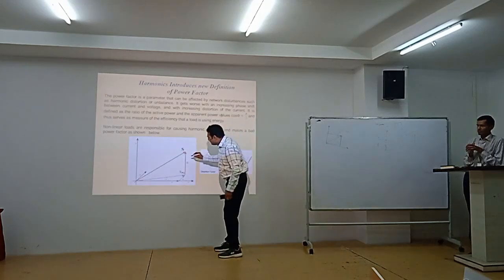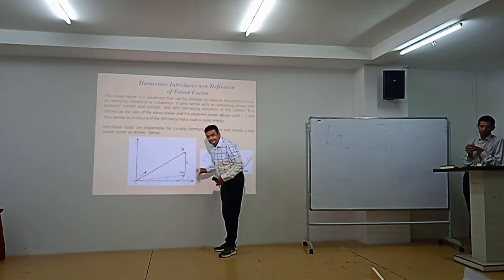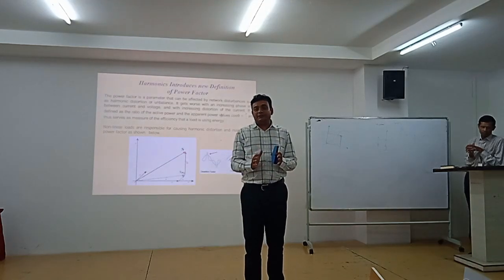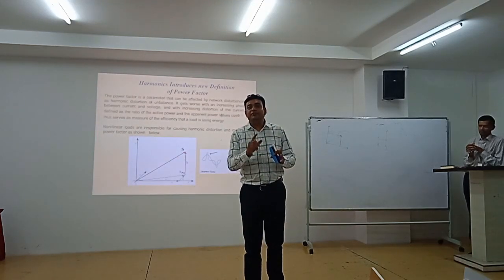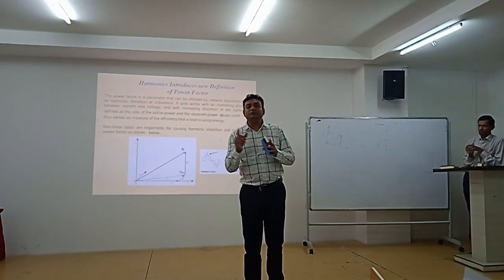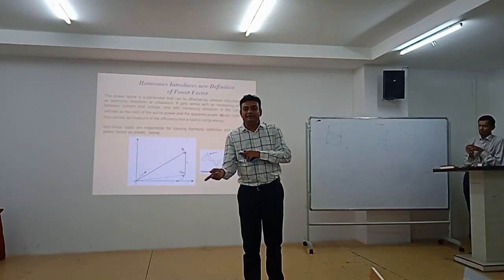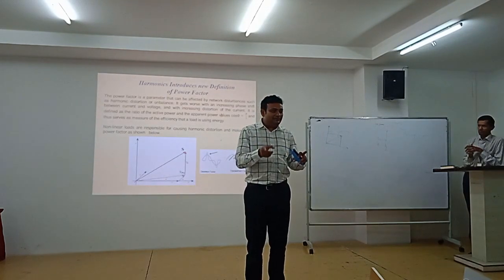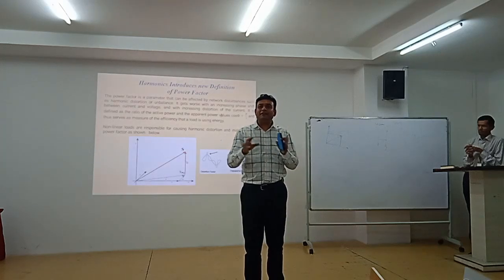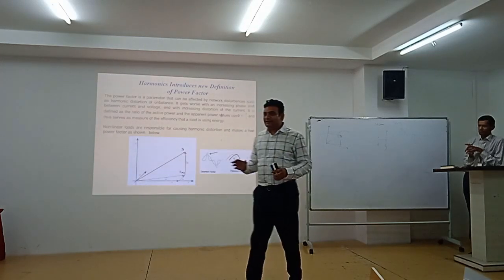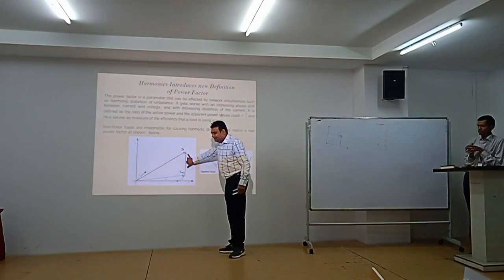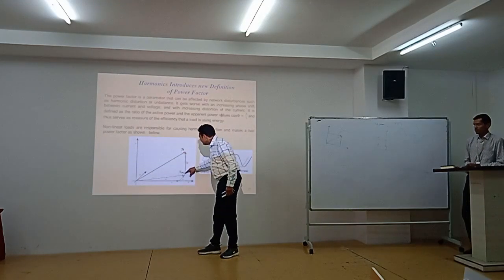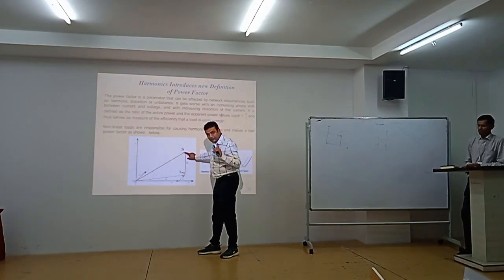This D is one more phasor added, and D stands for distortion. So all harmonic power means V2 into I2, V2 into I3, I2 into V3, I2 into V4. Right? Other than the fundamental V1 and I1, all other combinations are taken as distortion or harmonic power. So these you take as a reference. This is the third component.